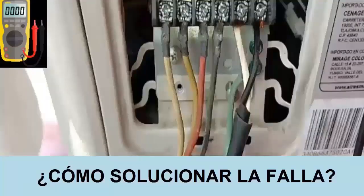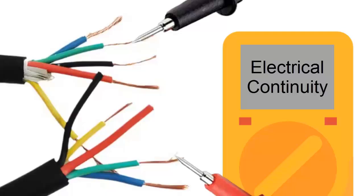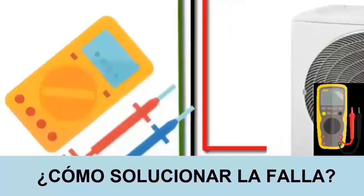C. Check all electrical connections between the indoor and outdoor units. Look for loose or damaged wires. If you're unsure about the signal cable, you can disconnect it from both units and use a multimeter in continuity mode to verify it has zero resistance or electrical continuity.